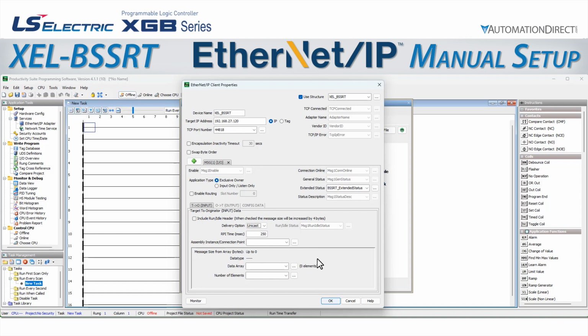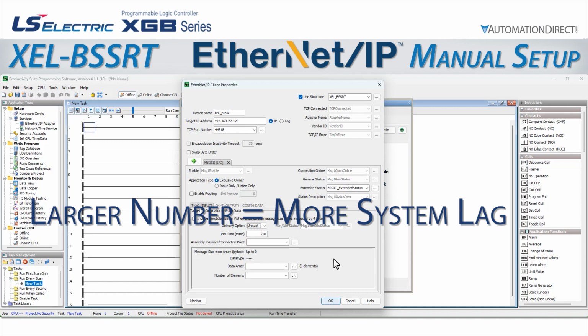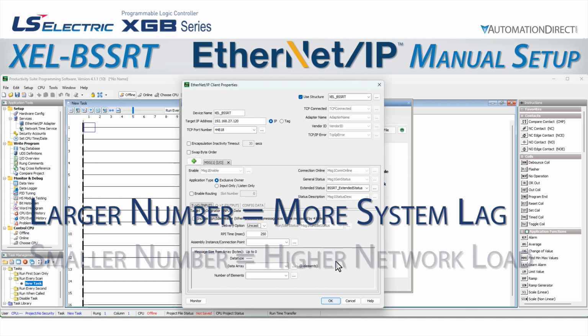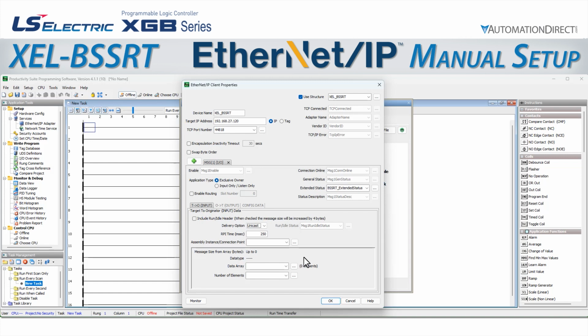RPI is determined by a balance of your I/O response needs and your available network throughput. If this number is larger, the lag between I/O changing and the information being seen by the scanner, in our case the PLC, will increase, potentially leading to poor system response. If it is smaller, the system response will be much faster, but the additional messages will increase the load on the network. If this gets too fast, the network can drop packets or even shut down altogether, depending on the networking hardware. For our RPI time, we will leave it at the default of 250 milliseconds.